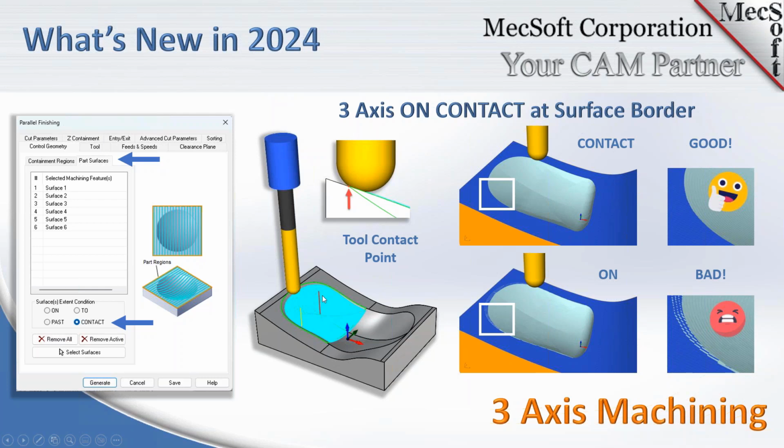And for cavity parts that have cavities, the tool is actually rolling up over the parting line, which is a big no-no. Tool makers do not like to see that tool ride that parting line. So in 24, we added a new condition called the contact. So whenever the tip, for example, if you're using a ball mill, whenever the machining ball of the tool makes contact with that perimeter edge of the surface, it stops, and then starts going in the reverse direction, or where it's supposed to go, opposite that direction.